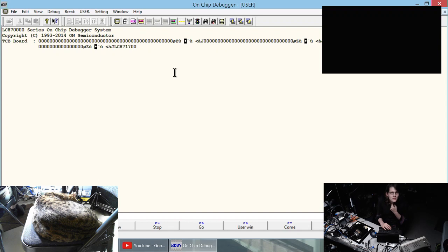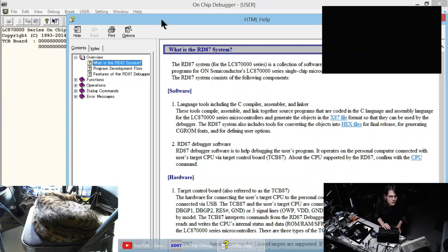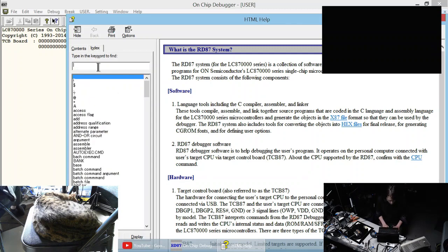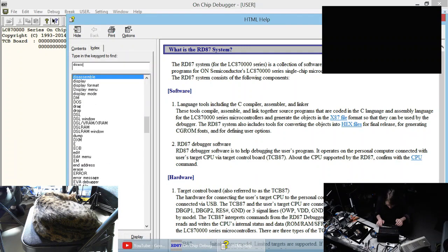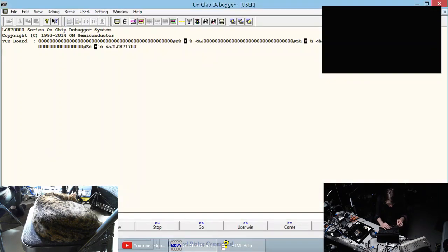Yeah, I think these strings are also something related to the board identity, and we're just giving back a shorter packet than it expects, so the debugger is kind of weird. I don't remember off the top of my head the command that disassembles target memory. I think it might be just D or something, but let's pull up the help just to make sure. I don't want to inadvertently send something that's unsupported and crash this. Oh. Helps if I use the right keyboard. U for unassemble. Okay. So let's try unassemble starting from 0 to like 1,000.